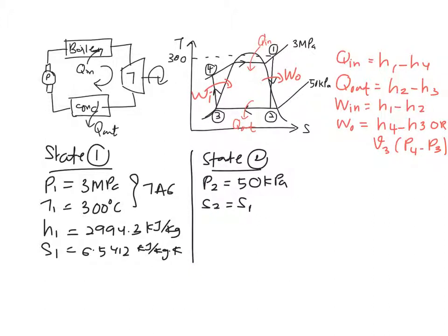Remember, we are trying to solve the problem of a simple, ideal Rankine cycle. When it is ideal, recall that we learned about entropy before. It is an ideal cycle where the entropy value at your inlet is equal to the entropy value at your outlet. What does it mean actually? It means that you don't have fluid friction that contributes to heat.